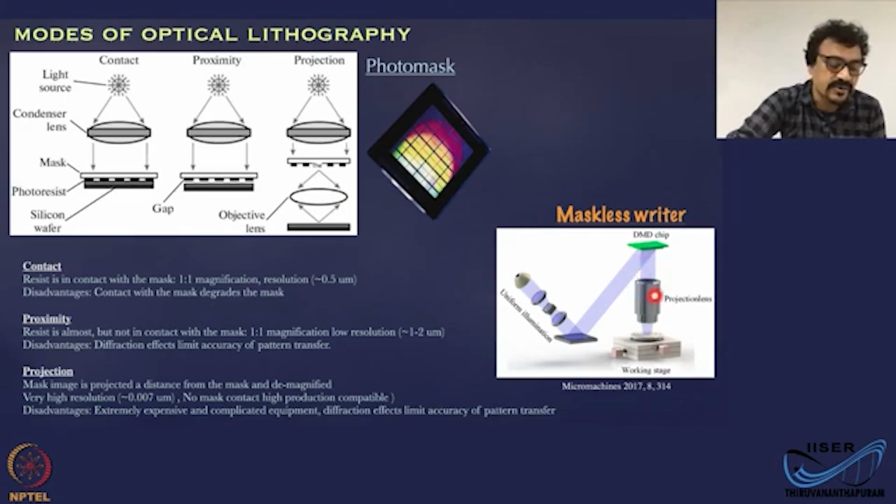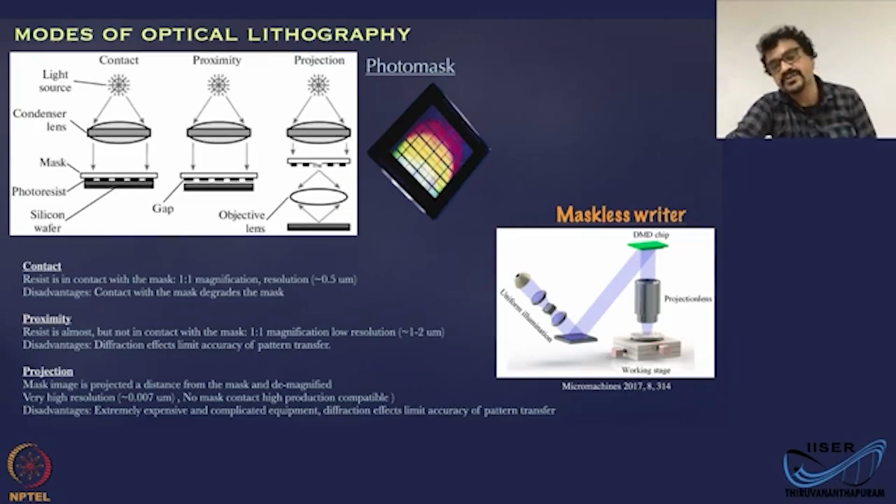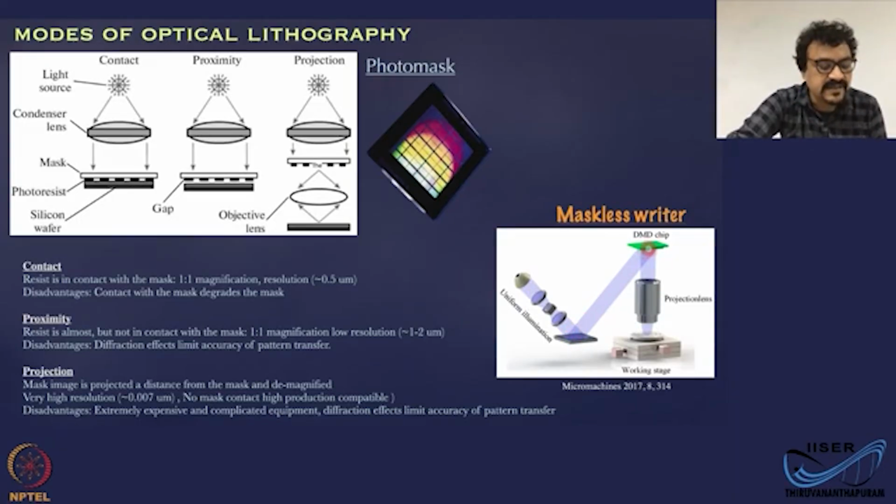that onto the substrate. So you have a light source, which is usually a UV light source, and all the associated optics with that. Then this is guided to the micro mirror. The micro mirror will actually project it onto a sample. Whatever the pattern here, that will get projected down to the sample. And there are of course optical systems which are used to demagnify this down to the sample.